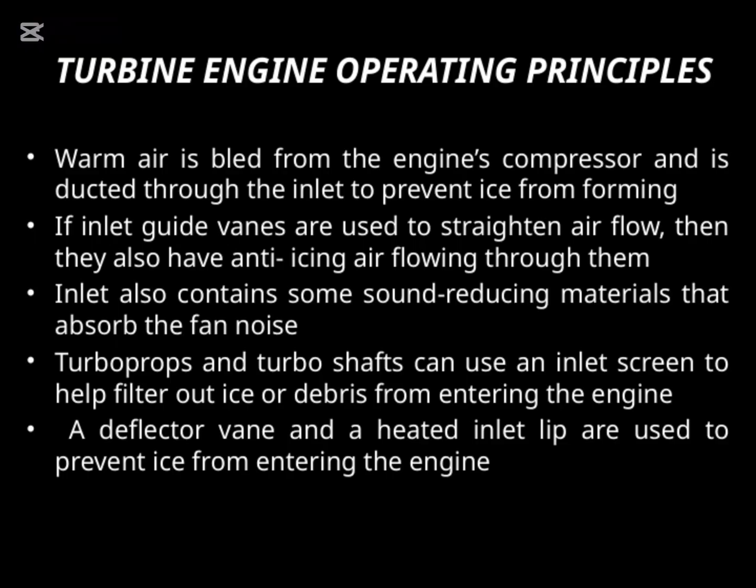Additionally, to further prevent ice entry, a deflector vane and a heated inlet lip are used. The deflector vane guides airflow effectively, while the heated inlet lip ensures that any ice attempting to enter is melted away before it can cause problems. All of these features work together to ensure the engine operates efficiently and safely, even in challenging weather conditions.